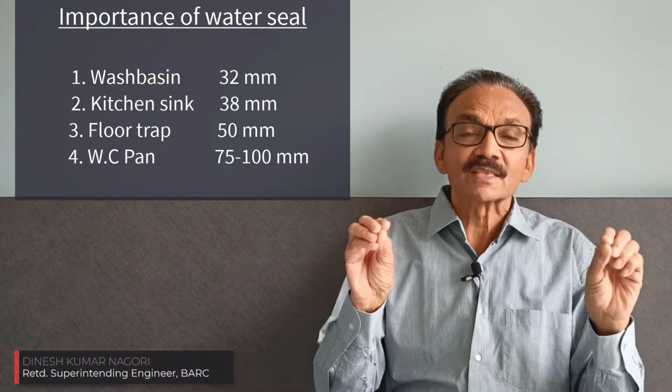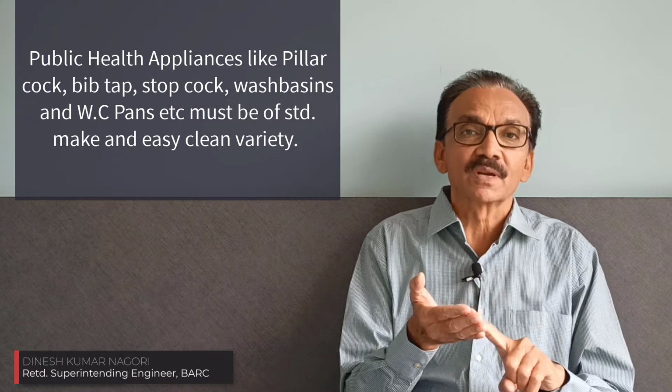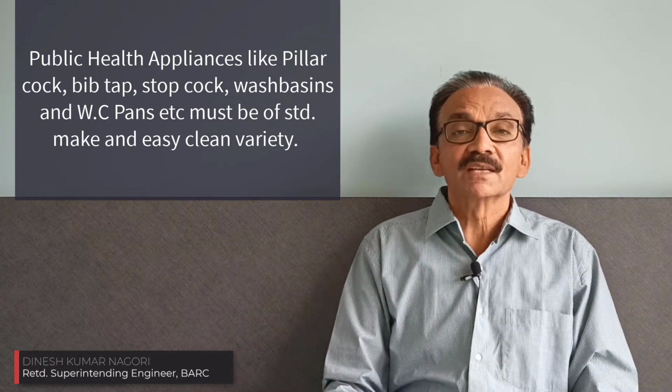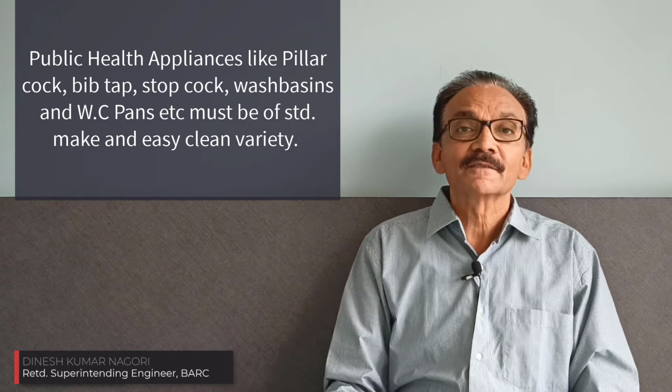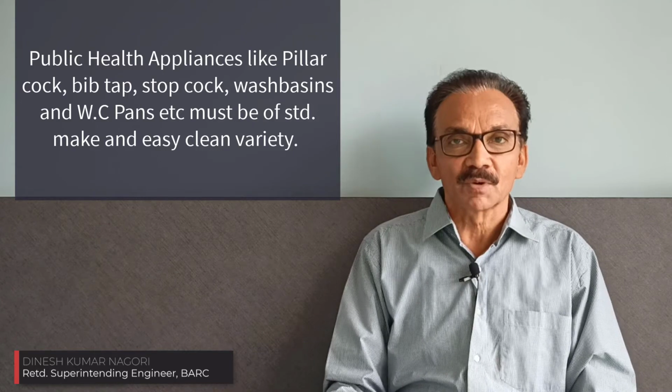amount on construction of a flat or building, you must spend a handsome amount on these public health items also, because they are in day-to-day use, so that the resident, whether you are an owner or a tenant, will not face any problem at a later date. For example, bib taps, bib cock, pillar cock should be of very good standard make and good quality. All these traps must be of easy-clean variety and of good material. So you must go for the standard items, don't go with the commercial item.